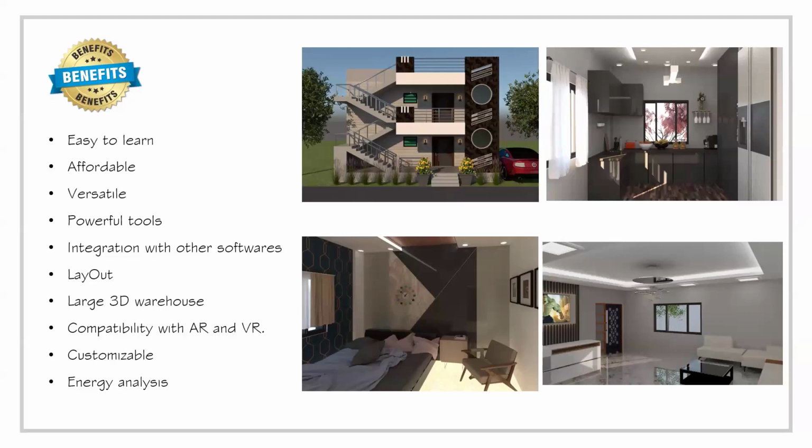It will show the shadows and lighting, and you can add plugins into SketchUp. There are so many plugins, but if you add too many plugins, SketchUp will become heavy. Just add the plugin, and when your work is completed, uninstall it. Otherwise the system will become slow, so don't install heavy plugins.